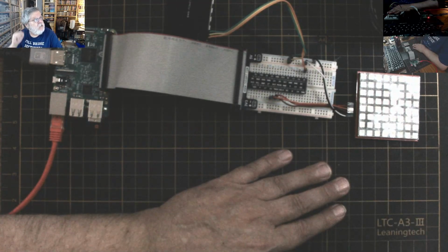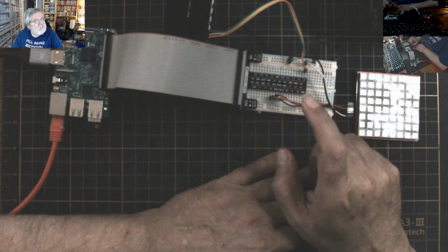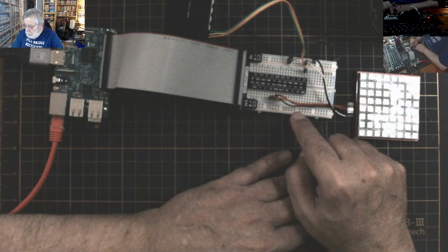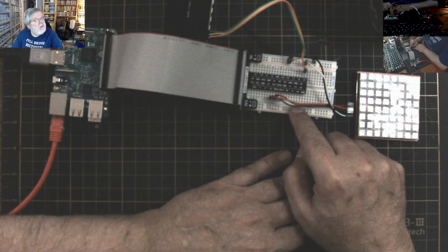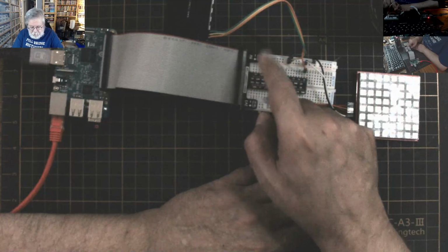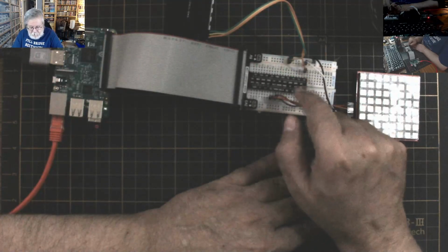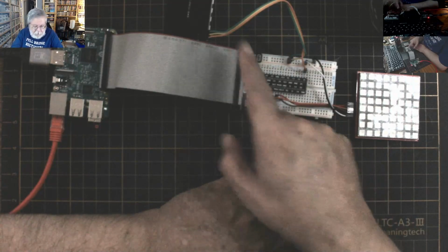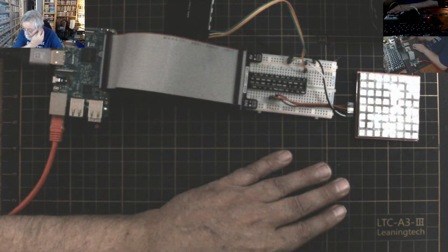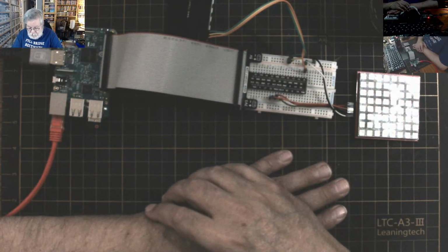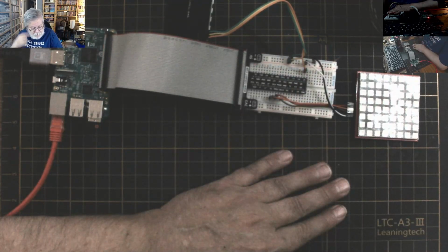Another piece you're going to need is something to pin to the GPIO. Now I chose this guy right here. This is what they call a T-bar for GPIO pins for Raspberry Pis. You plug them into your breadboard, you plug the ribbon cable into your Pi, and thus you have a breakout for all the pins. And it's kind of easier to work with.